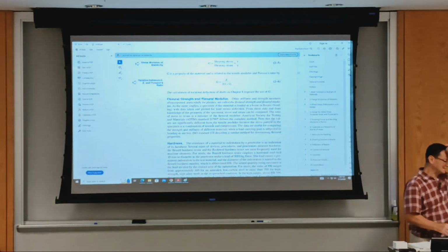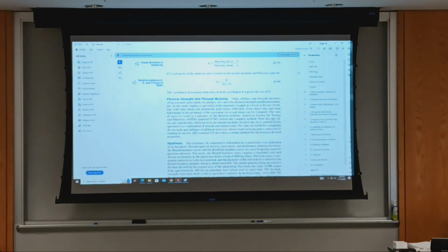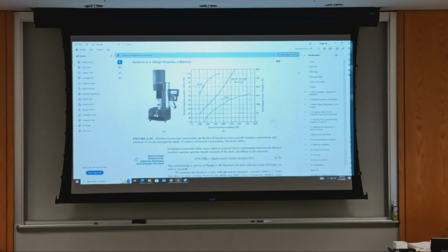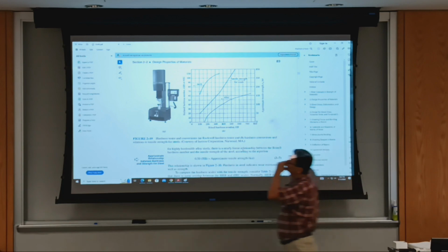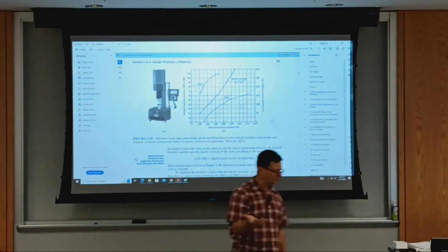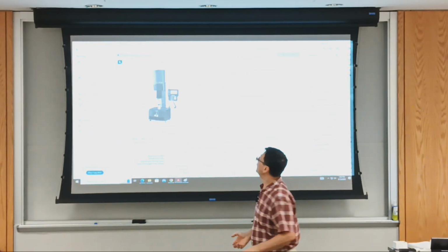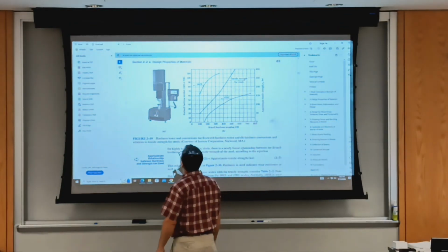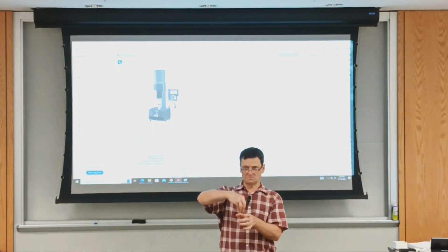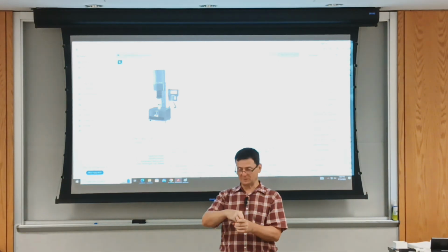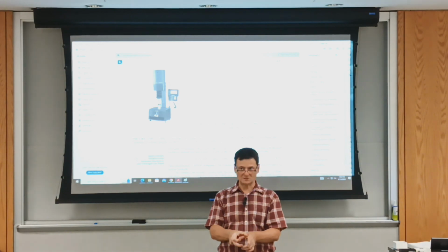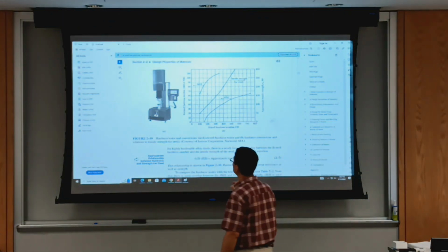So regarding hardness, the first way it was done is to use an indenter. You press it against a flat finished surface. It should be a smooth surface, so you need to polish it to where you can measure the indentation. In the Brinell hardness test, you force a steel ball against that prepared surface, and you measure with a magnifying glass the diameter of the indentation. The ball itself is standardized.